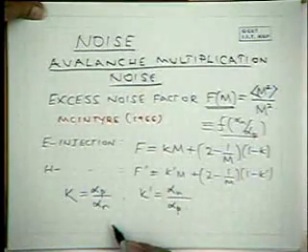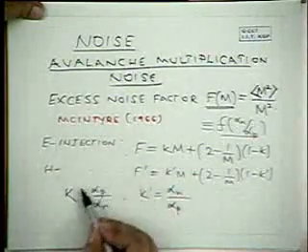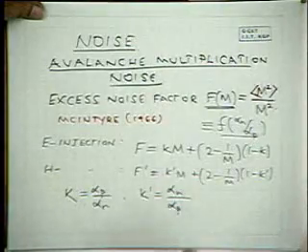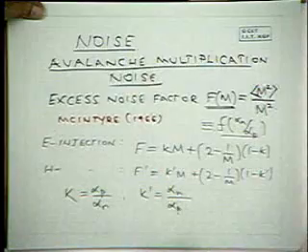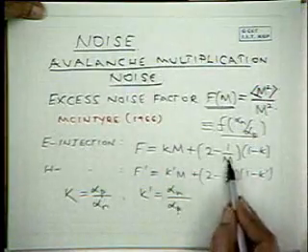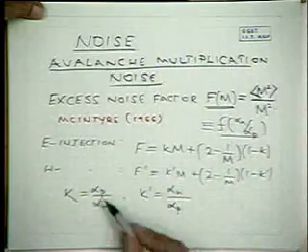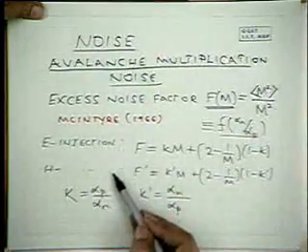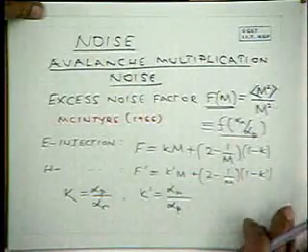So you see that the two cases differ. Why? Because alpha n and alpha p are not the same. Obviously the effective masses also come in and play a role, and m also comes in. So, depending upon the material, depending upon k or k', we can choose either electron injection or hole injection. Now let's take special cases for these.